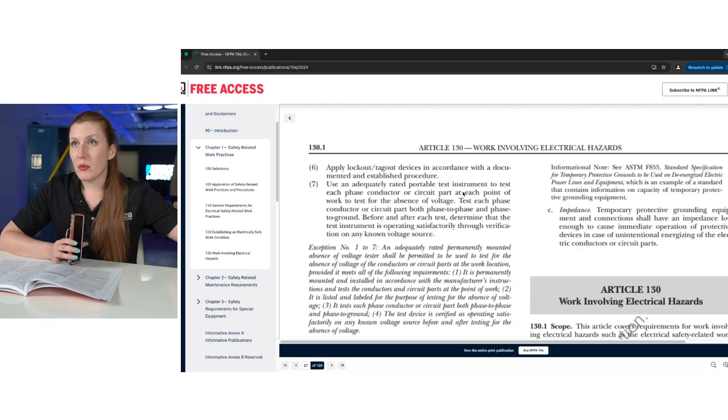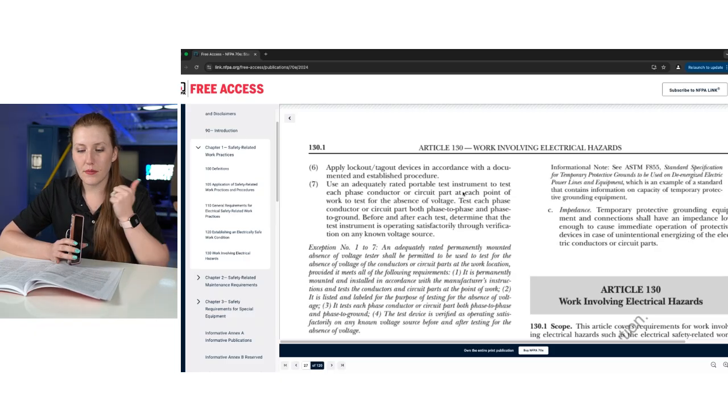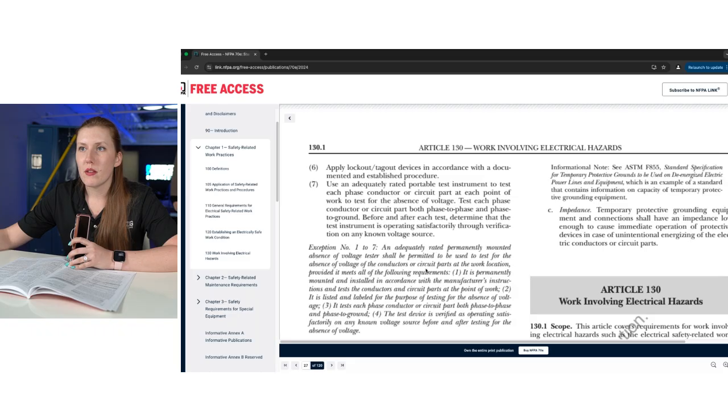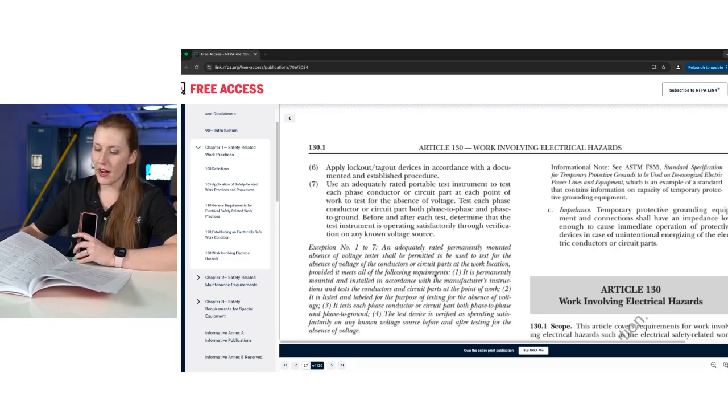I still hear a lot of people say, well, to turn off a disconnect, you open it up to get that visual verification that the blades are open, so I go ahead and do my live, dead, live right there. Great, fine, still do that, but you still then have to do your live, dead, live where you're sticking your hands, okay? So that clarification there, just to make sure that people don't miss a potential hazard. Again, this wasn't really too earth-shattering for those who had understood the intent of the standard to begin with, but there were some common misunderstandings in this verbiage, so they clarified it.